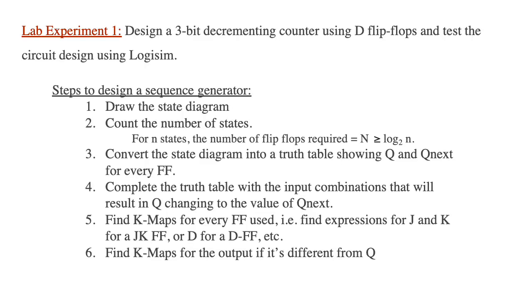We'll start with the first experiment of this lab. The experiment requires us to design a 3-bit decrementing counter using D flip-flops and to test the circuit design using Logisim. Just to refresh our memory on the steps required to design a sequence generator, you can read them on your own or pause the video for your reference.